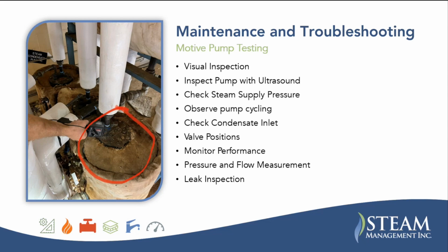You also want to ensure that everything's properly connected and condensate is flowing. You can check the steam supply, make sure it's at the correct pressure and temperature. Often the regulators for the steam supply fail, and those need to be replaced. So you might be getting too high of steam,